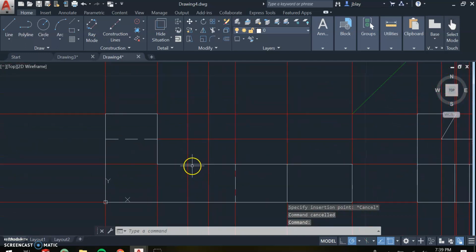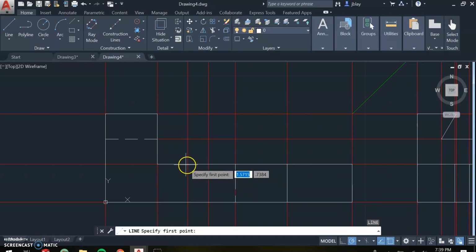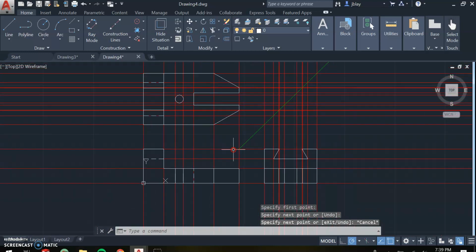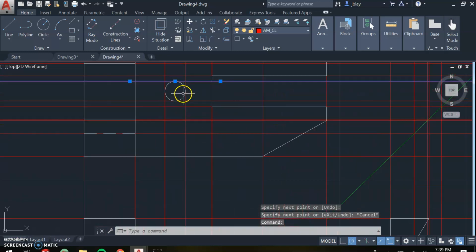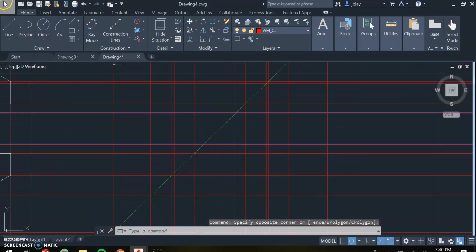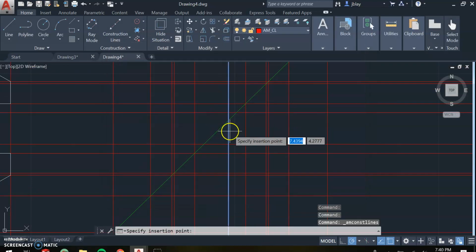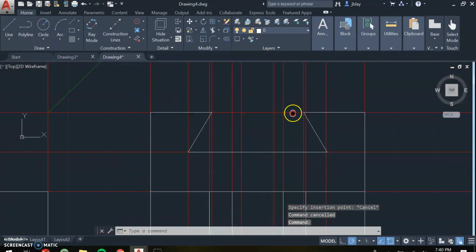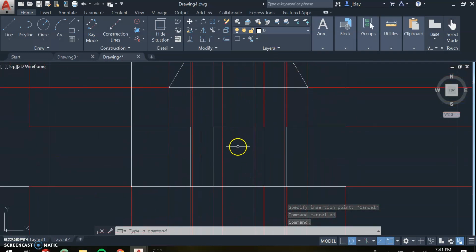So where I have those construction lines vertically, I will have two hidden lines right here. Horizontally, my construction lines go. You can zoom in and select them so that you know exactly which ones you're working with. So we're working with this one and this one. And we'll draw construction lines vertically through those two points where those intersect the miter line. And then we know in our right side view, we're going to have hidden lines right here.